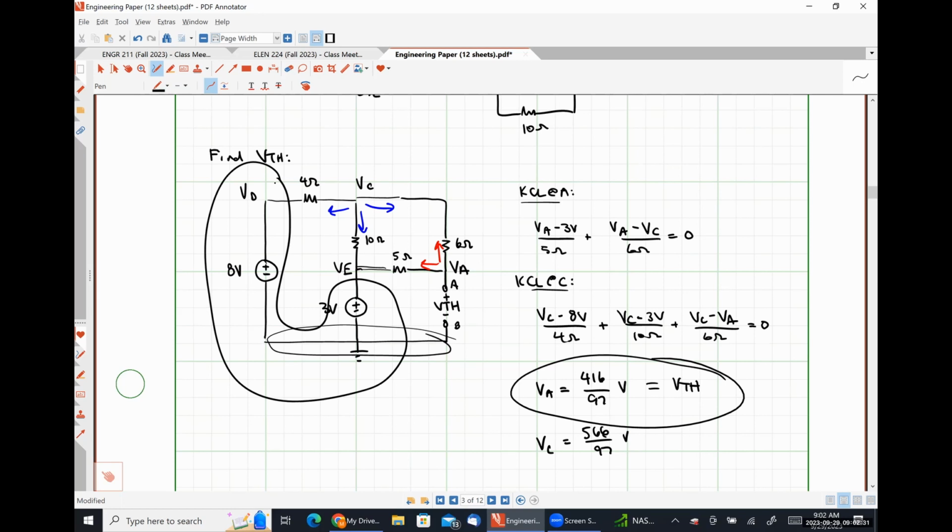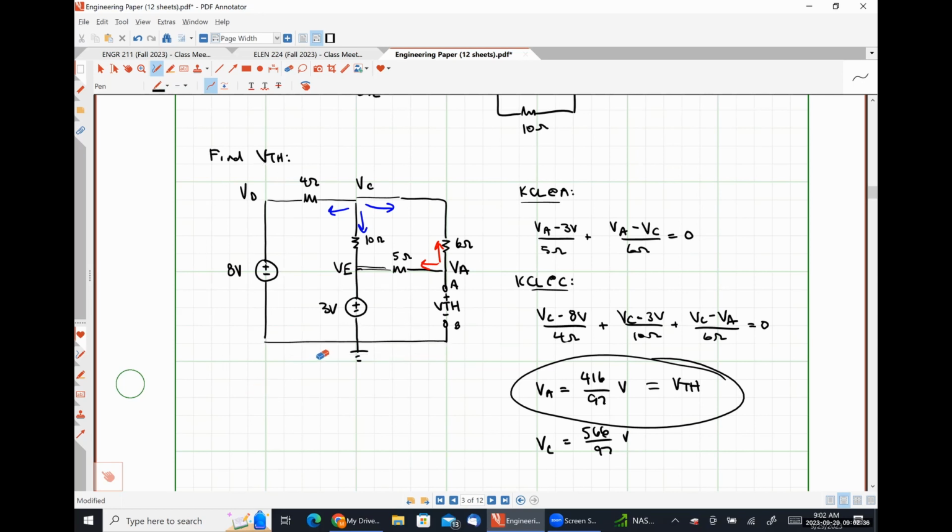So if, for example, there had been a resistor right here, I couldn't have done what I did, because now my 8 volts would have been between this node and whatever this node was labeled. So I couldn't have written this equation right here as it is.